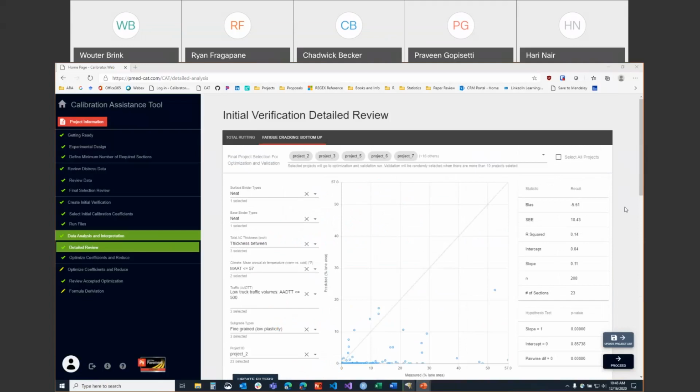All right. And we have another one here that says, what are your recommended values of tolerance bias for each type of distress for AC pavements? I would follow what the manual of practice does show. There are some recommendations in the guide itself, and you can try and compare it to the global models.